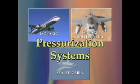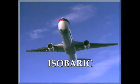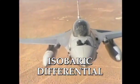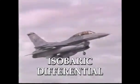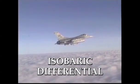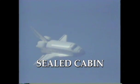Remember, there are 3 main types of aircraft pressurization systems. Isobaric, where the cabin altitude is preset and remains so throughout the flight. Isobaric differential. This one is mainly used in military aircraft. Upon ascent, the cabin begins to be pressurized until it reaches a preset altitude. If the ascent is continued, a constant pressure differential is maintained. Sealed cabin, used only in spacecraft.